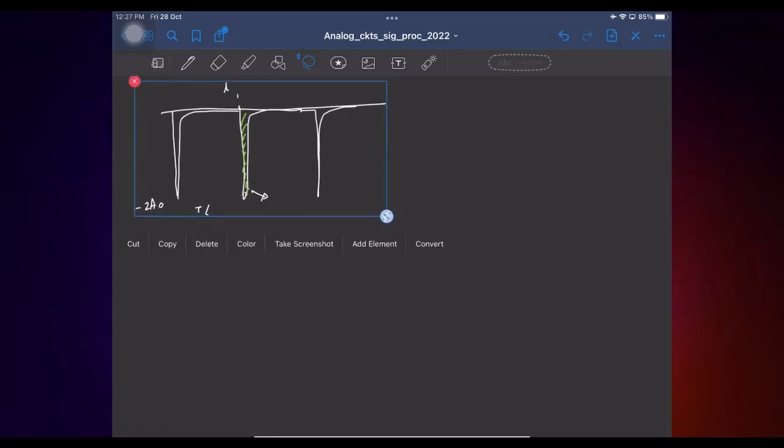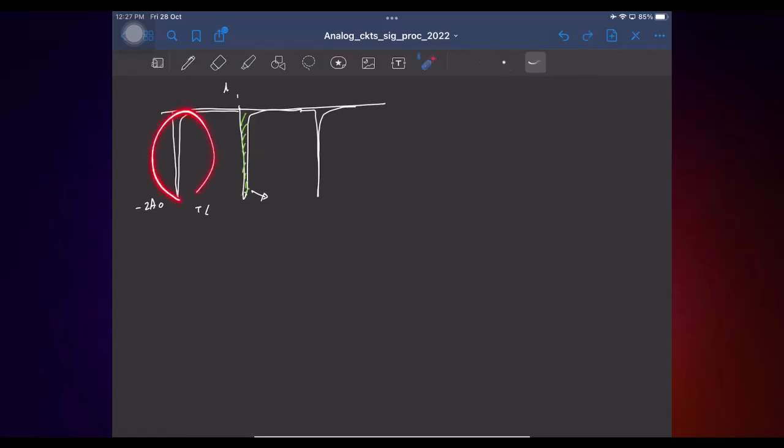So now we had just approximated this waveform as an impulse and calculated the Fourier coefficients. That will be valid for low frequencies where you are only interested in the average, but at high frequencies the approximation will not work. So let's say this waveform, one period of it, I'll draw it here. It looks like this, and this is minus 2A0 e power minus t by tau.